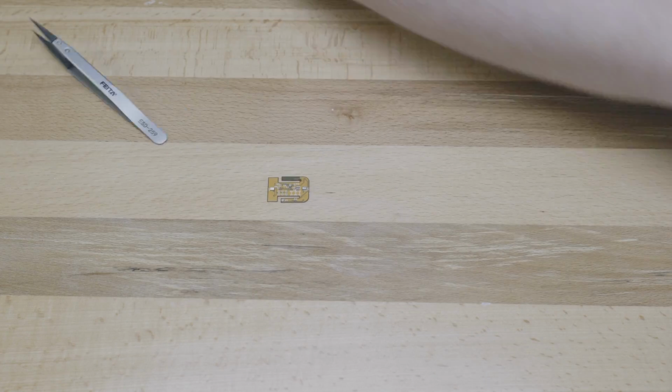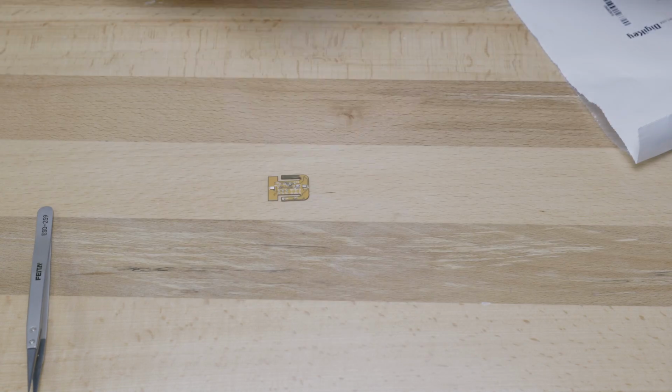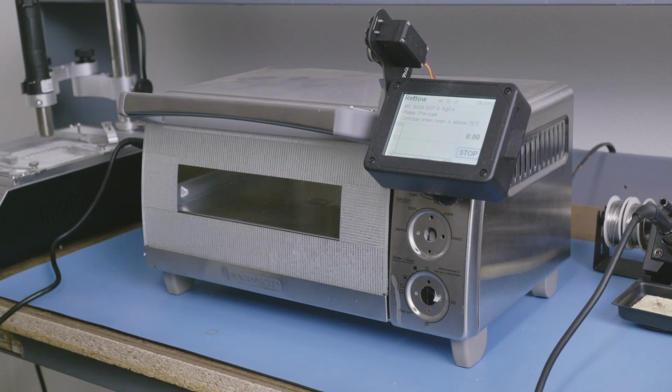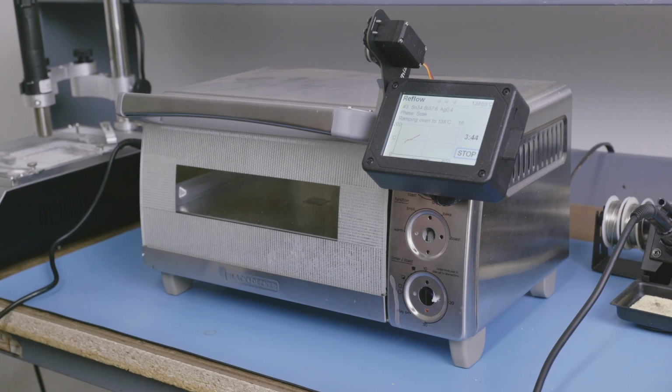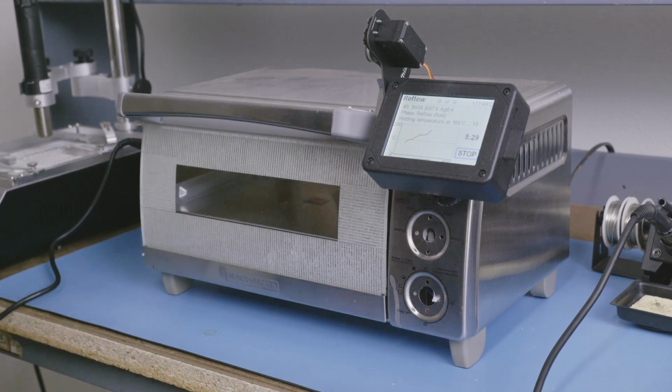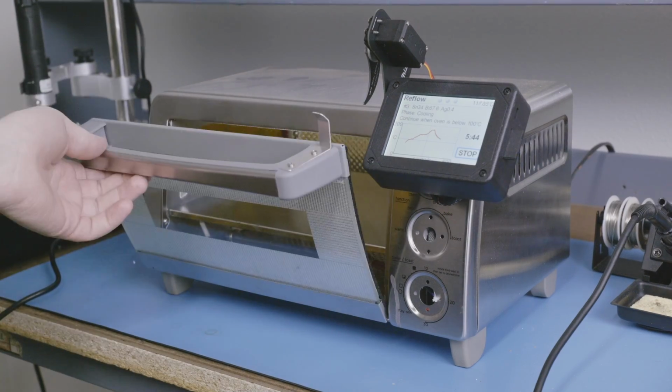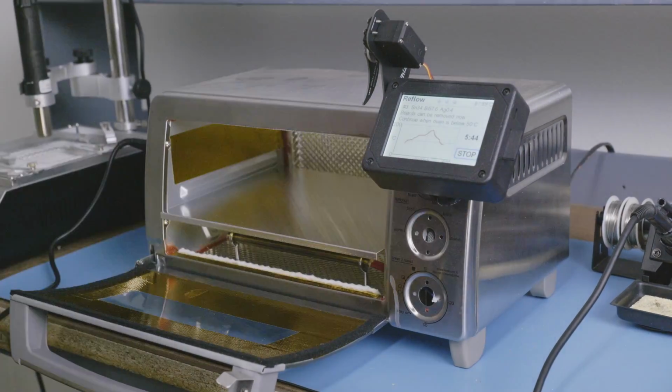I'll then peel the stencil off, fix any solder paste areas that need it, and pop the components on. Throw this into the oven real quick. I'm using a Control 3 that I built from a kit out of a toaster oven. Now the kit's about $300, which does seem like a lot, but I believe these ovens work substantially better than some of the other low-cost options, and you do get quite a complete kit for the money. I already have the profile set up, so all I have to do is hit start.